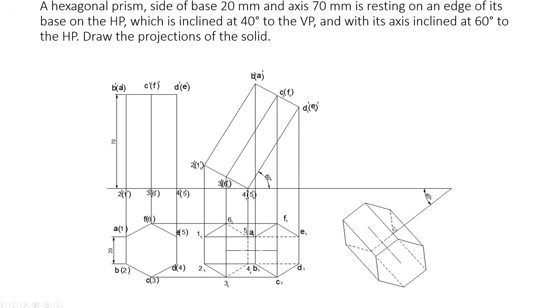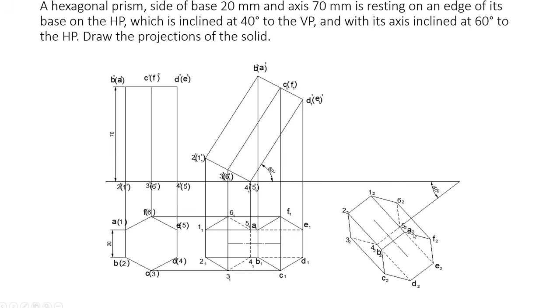Now once you connect those lines, you will get a hexagon. So in that hexagon also you want to keep some dotted lines. Whatever lines are coming invisible in this diagram, you want to copy those lines as it is. Name those points with suffix 1, 2. Here it is suffix 1, so here it is suffix 2. 1 2, 1 2, 2 2, 3 2, etc. All the other points will be A2, B2, etc. Now that means you copied this diagram here at 40 degrees.